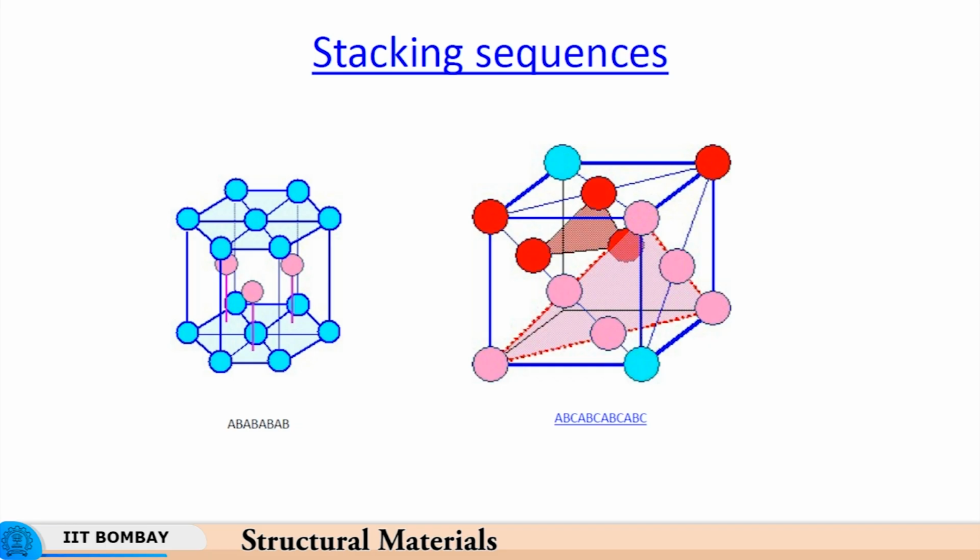I have been telling you that dislocation movement gets impeded, and therefore you need to apply an increasing amount of load. The stress continues to increase, and that we call work hardening. But the question is, can the work hardening go on forever? The answer is no, because as work hardening continues, the so-called stored energy of cold work in the form of dislocations continues to increase.